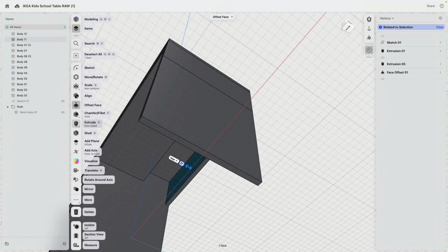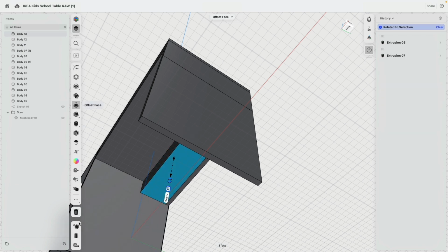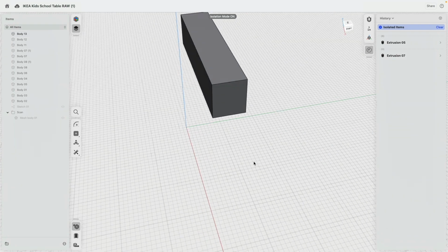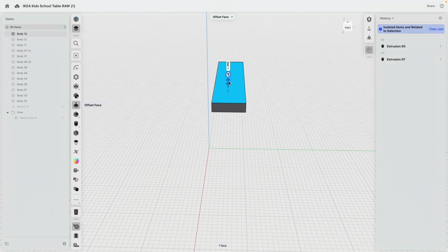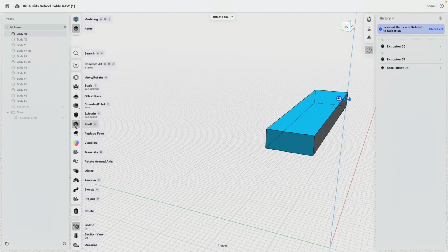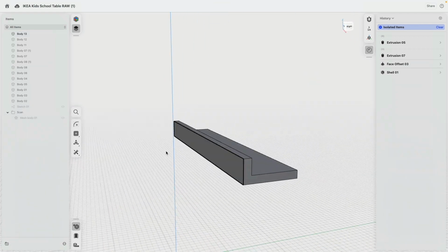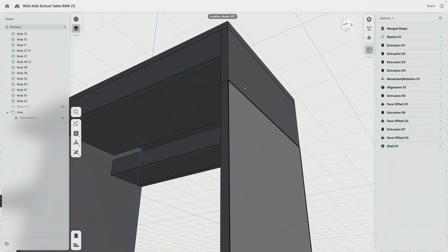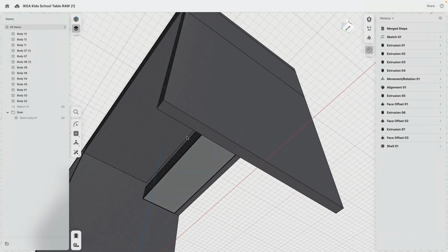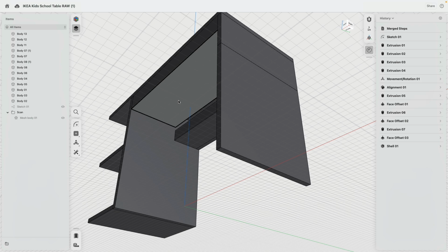Okay, so this one we extrude out 7 inches, but as a new body. So that object we select and go isolate, because first that rip we can move down, let's say to 3 inches, and then top face, back face, left face, right face, shell, and 1 inch. Look at that. See? Super easy. Cool. Okay. That actually works really good.